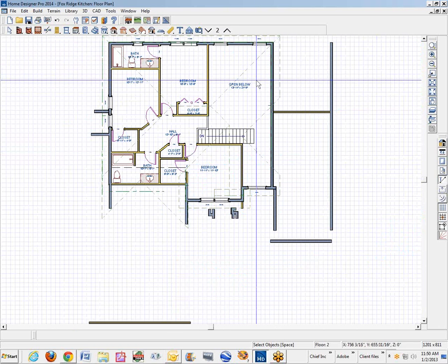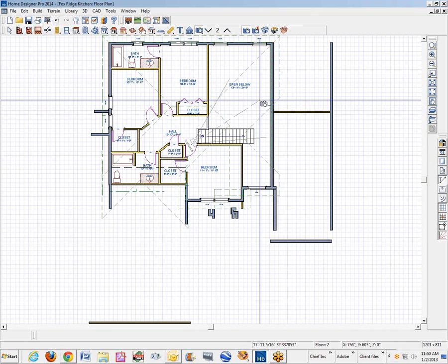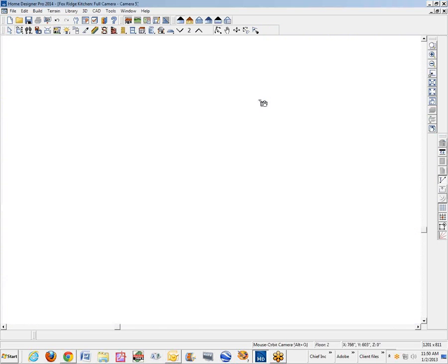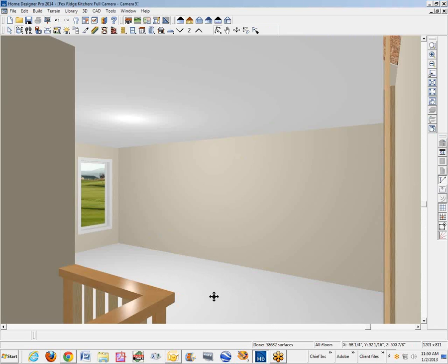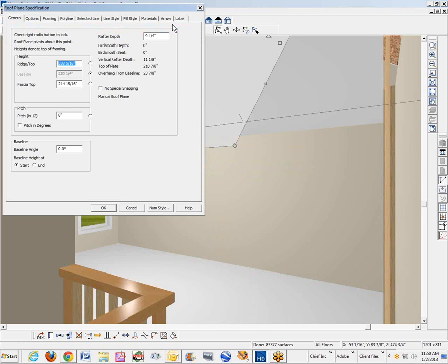So anyway, the only thing that I found that worked was very simple and straightforward. The first thing I tried to do was just figure out where this material was coming from. I would click on it and I would get a roof plane. I clicked on this here and I got the roof plane. So that indicated to me that the roof system is all messed up.